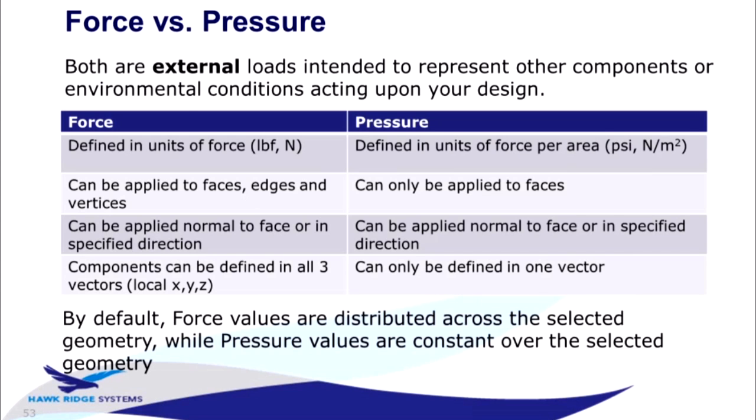But first of all, another thing we don't get a question about often, but it does occasionally come up, is, what's the difference between a force and a pressure? Does it matter which one I specify? And the short answer is no. A force applied to a face becomes evenly distributed across that face, unless you set it to something non-uniform.